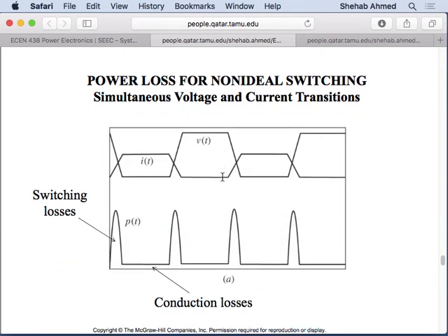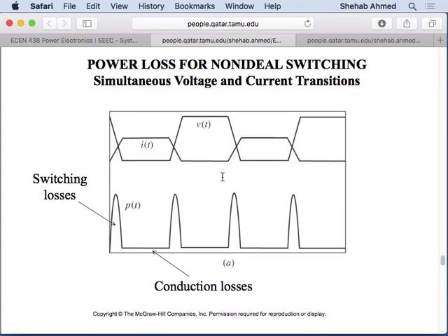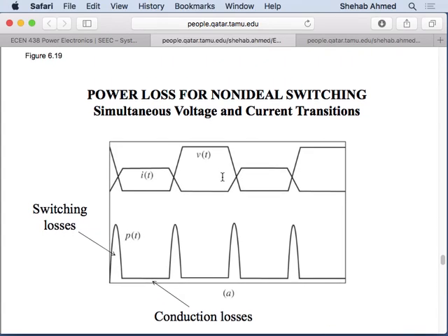The discussion on switching loss, I think I will have to wrap up next time. So then, what we did was we looked at all the converter topologies. We looked at how to select switches for all the inductor topologies. You select switches based on peak voltage across the switch and average current, right? And then we selected inductors and capacitors. So we selected the circuit requirements of inductance and capacitance, and then we looked at how to select real inductors and capacitances. Real capacitances, we looked at ESR, the effect of ESR and how it will change the value of capacitor that you select.